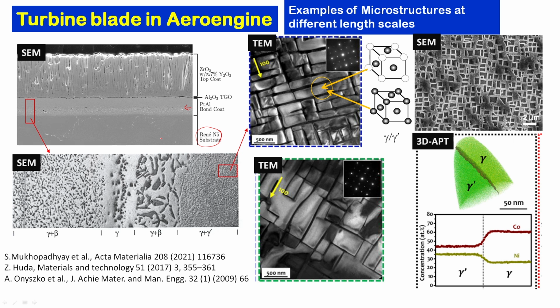That is why an underlying platinum aluminide layer is kept between the two, and this can get oxidized and form thermally grown aluminum oxide on top of it. So it is a very complex structure with four different layers: zirconium dioxide, thermally grown aluminum oxide (TGO), then the bond coat, and then the superalloy.